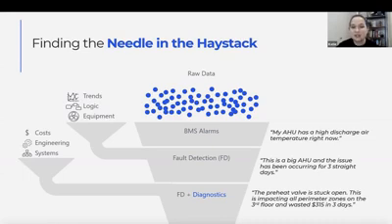When we say FDD, we're talking about fault detection and diagnostics. That last little D is really the big important piece, and it assigns a cost to the problem. It does some engineering, and it also knows what other systems might be impacted by that. So the example here, with one more level of detail, would be the preheat valve is stuck open.